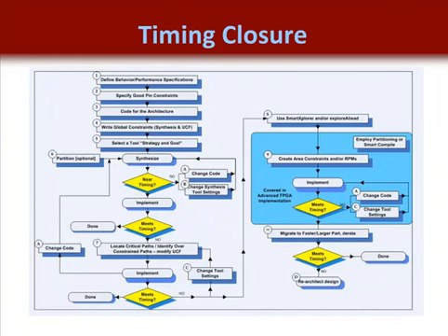Now, step 6 is to synthesize the design. After synthesis, most designers are evaluating the HDL code associated with their timing critical paths. This is very smart. As you'll learn, your HDL coding style has perhaps the largest impact on the speed and the size of your design. So the smartest designers are busy isolating their timing critical paths, that is, those paths that fail to meet their timing constraints, with their schematic viewer and then verify that their HDL is optimal.